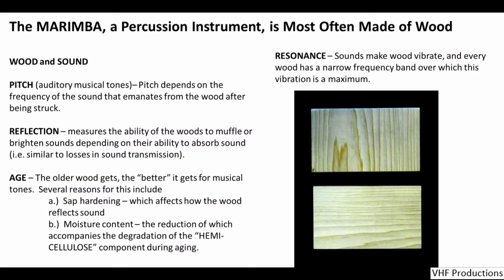Some of the wood properties of interest for making musical instruments from wood is the density of the wood, with slower sound decay resulting from higher density. A higher density wood also makes them mechanically stronger, which is important for percussion instruments where you're going to be striking the wood. Too soft or too low density wood would result in indents being created after being struck.